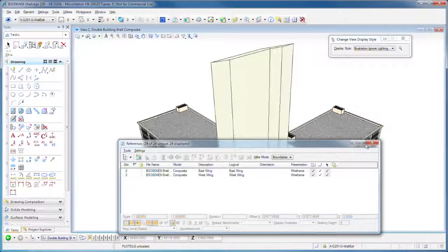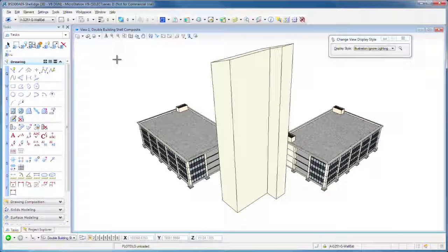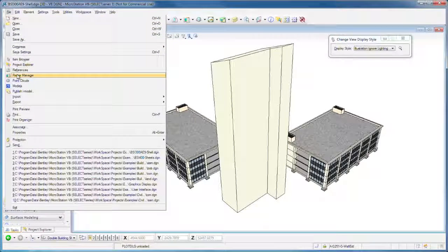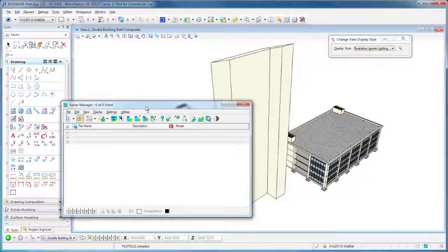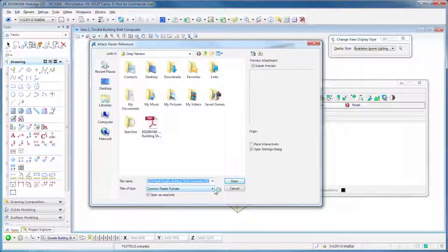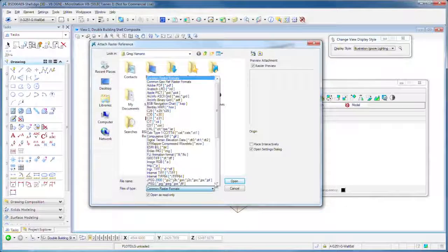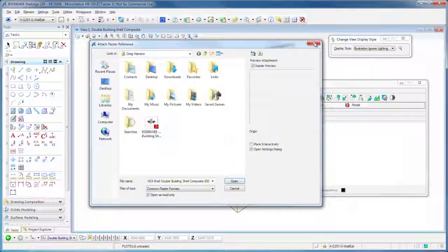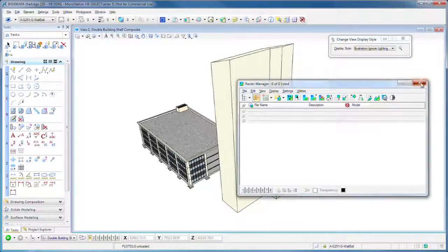Now, in addition to those kinds of files, which are 3D vector models, we can also reference raster files. The raster files are like photographs. And in that case, the formats that we can reference are an enormous number, certainly JPEG we know well, TIFF is very popular. There are some geo-coordinated photographs that have a longitude, latitude fixed, and we can bring those in absolutely. So we won't spend too much time on the raster referencing right now.